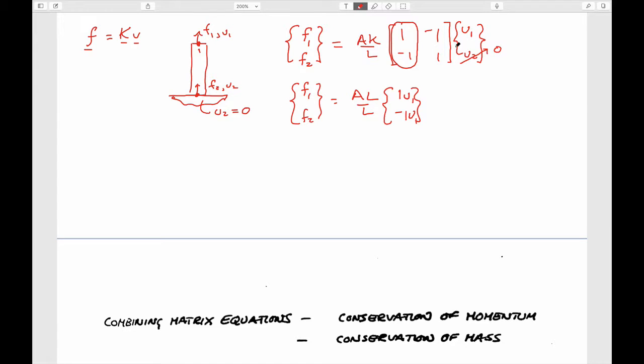If we apply a unit displacement, say plus 1, in other words we're pulling it up by plus 1, then the magnitudes of these terms within the matrix physically represent the forces that would be applied in this equilibrium system to satisfy that geometry, that is, one node is pulled to a magnitude of 1 and everything else is left not moving.